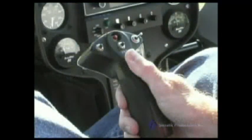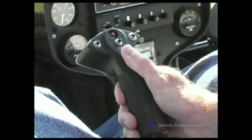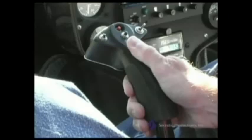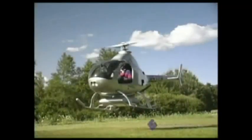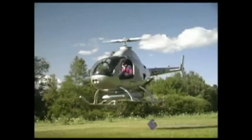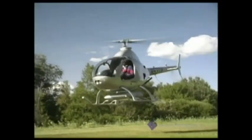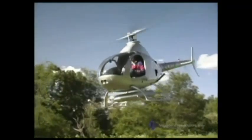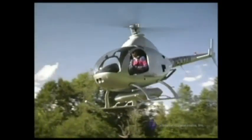Now is when the cyclic control comes into play. When moving the cyclic control, the total rotor thrust will also move. For example, pushing the cyclic slightly forward causes the total rotor thrust to tilt forward. This will reduce the lift component and create a thrust component. Since the helicopter now has thrust, it will begin to move forward. It will continue to accelerate until the air resistance causes enough drag to equal the thrust, and then will stay at that speed. By tilting the total rotor thrust in any direction, we can move in any direction.